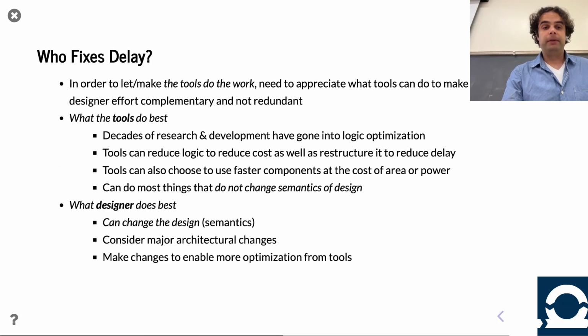Cool. So, like I said, how can you fix the delay? The tools can do a lot, and you want the tools to do a lot. Remember, one of the themes of this course is make tools do the work, right? And there's decades of work in EDA to try and improve this. They can do a lot. But the key thing the tools can't do is change the semantics of the design. So if you have specified in your RTL a certain behavior, they can't change that behavior, right?